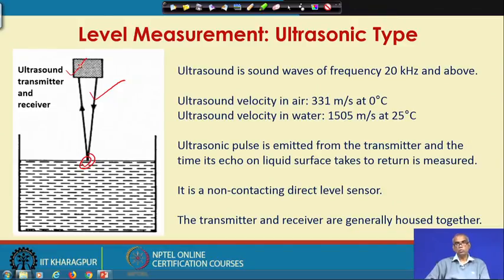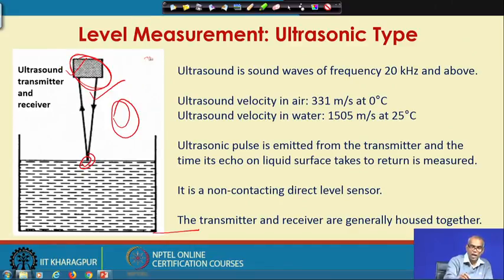If I now know the velocity of the ultrasound in this medium, I can find out the distance the ultrasound has travelled. Since I know the exact position of this device, let us say from the bottom of the tank, I can find out this difference easily.